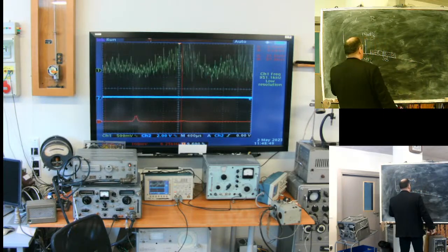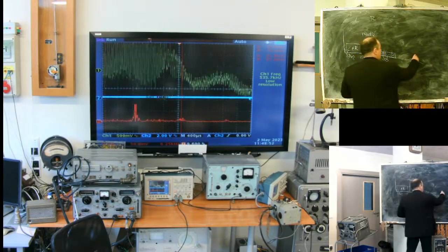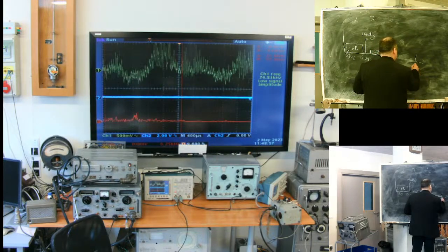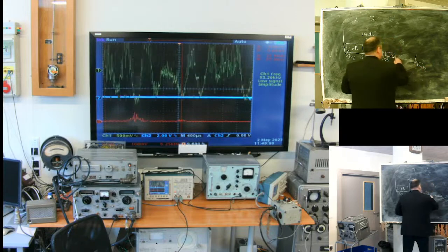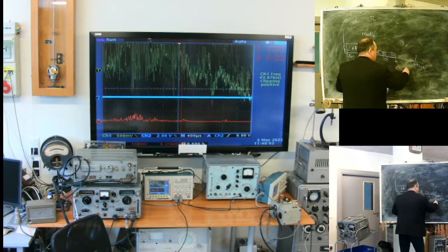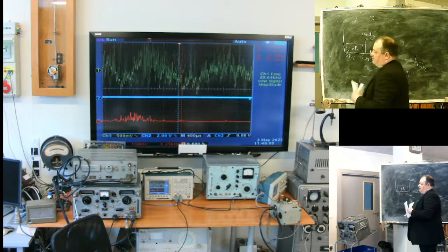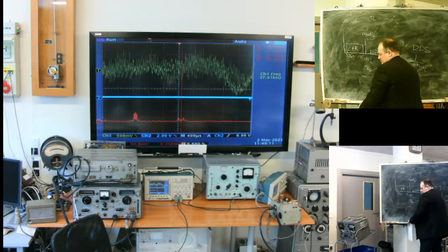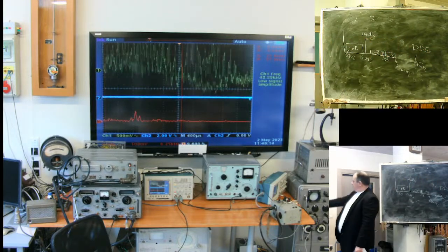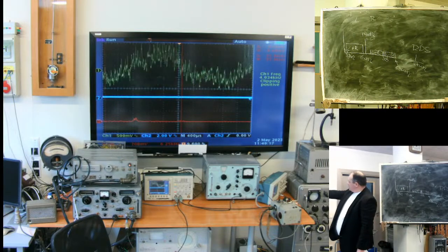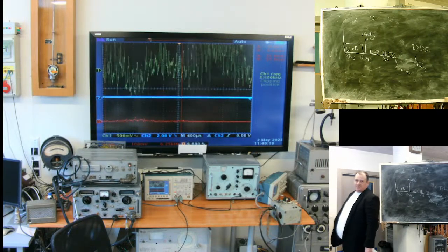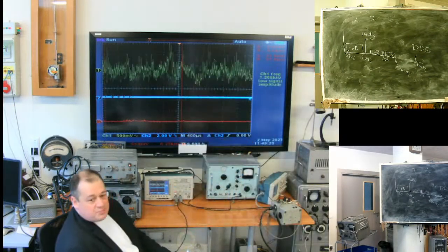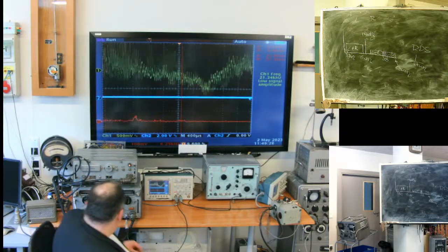And next one, triple pilot. What should it be? It should be 57. This one ends at 53 kilohertz. And what about 57? RDS. Here around the red line, a data stream appears. It's the name of the station, the track playing, weather, and so on.